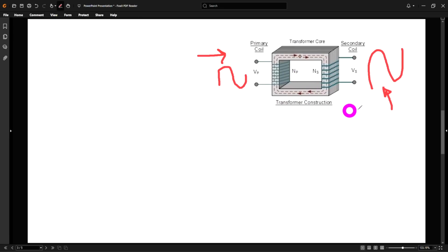As a result, the amount of power I get at the output will always be less than the amount of power I put in because it's a passive structure. And even if the transformer were ideal, it would only become 1-to-1. There are many other problems. A transformer would not go down to DC, so we will not have DC gain through it.